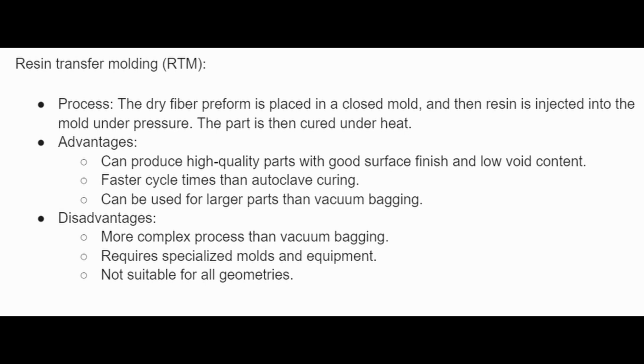Advantages: can produce high quality parts with good surface finish and low void content. Faster cycle times than autoclave curing. Can be used for larger parts than vacuum bagging. Disadvantages: it's a more complex process than vacuum bagging, requires specialized moulds and equipment, and not suitable for all geometries.